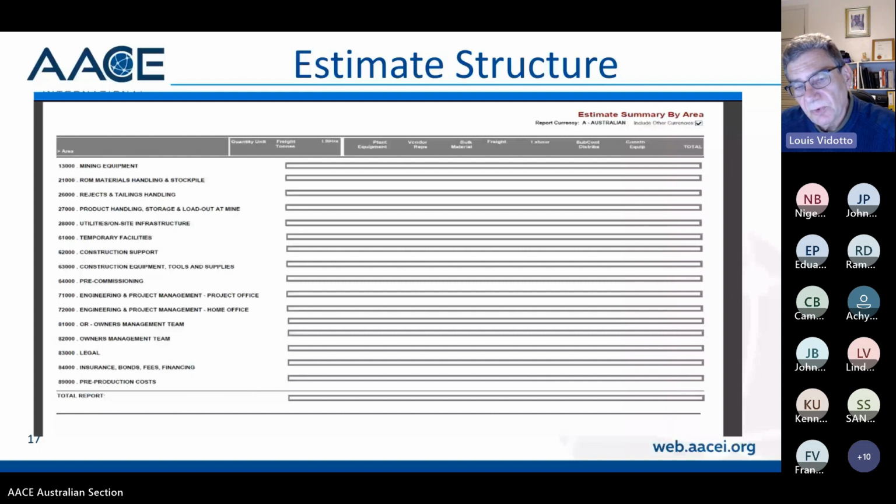And that's why it's important when you're building an estimate to know what your execution strategy is. Certainly an earthworks contractor is going to have bigger overheads than an electrical contractor. So in terms of equipment used and things like that, labour rates will be different because an electrical contractor will have probably higher labour rates because he's using specialty electricians, etc. Whereas an earthworks contractor will have more labour, although equipment operators cost a fair bit as well.